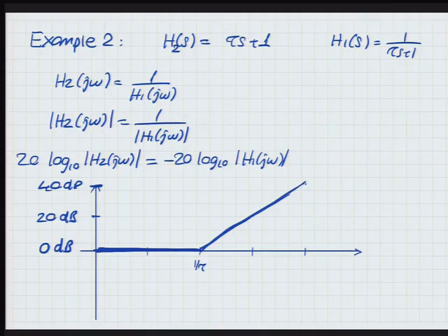Okay, makes sense? And of course, if you were to plot the actual frequency response, it would not have a kink like this. It would more smoothly bend over, and you would get 3 dBs of error at omega equals 1 over tau. Right? Same idea, really.